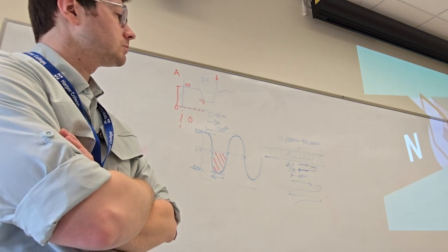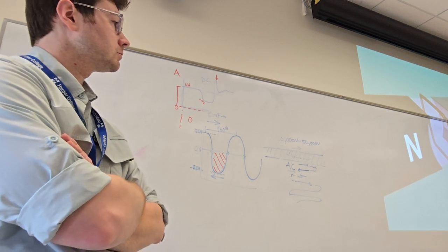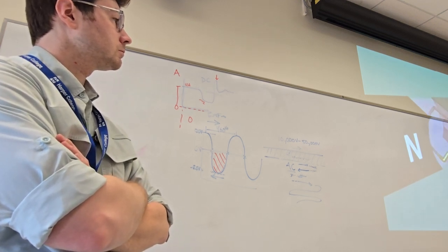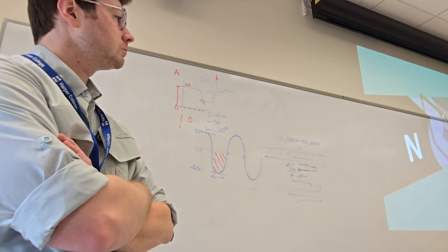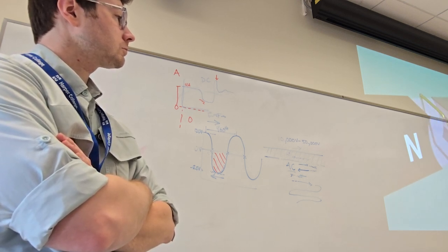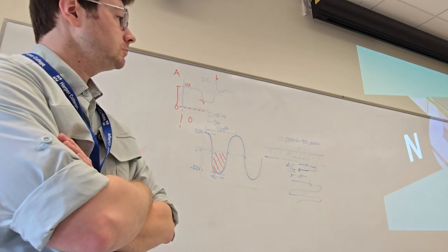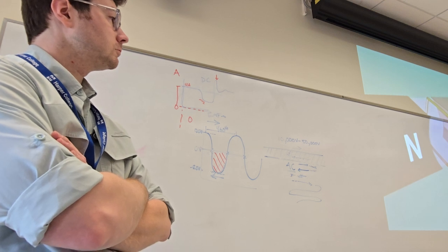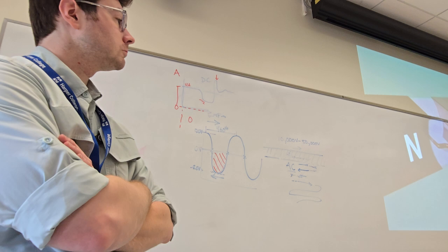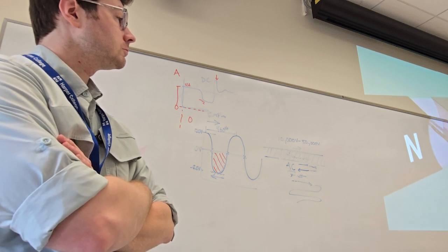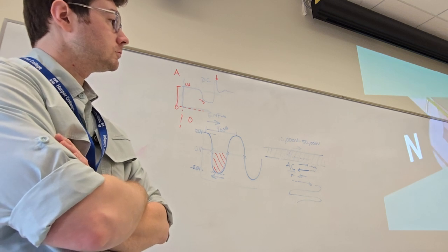Carbon-impregnated brushes provide a sliding connection to the commutator to complete the circuit and allow current to flow through the loop. Rotation commences with both sides of the conductor loop cutting the stationary field. When the loop passes the point where the field is no longer being cut, the momentum of rotation carries the loop and the commutator segments over, so that the brushes maintain current flow in the same direction in each side of the loop relative to the stationary field.